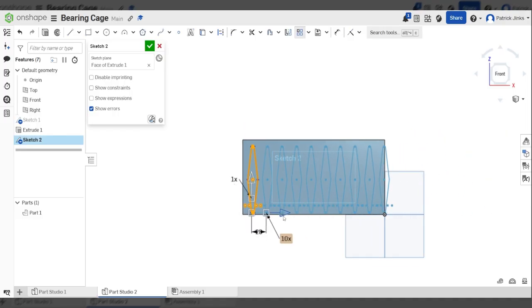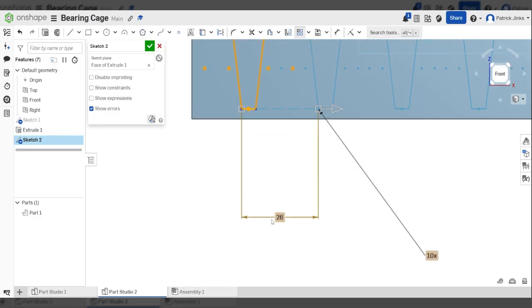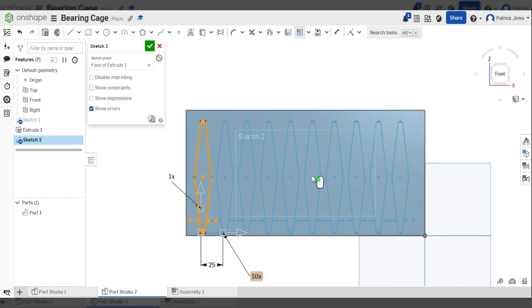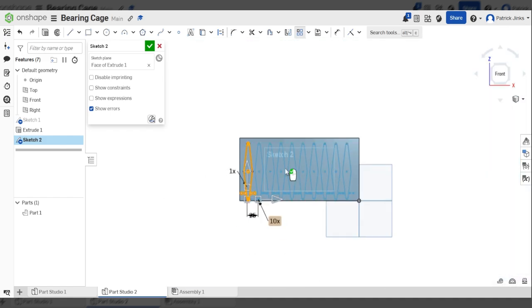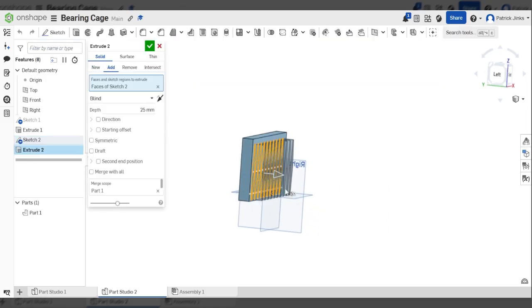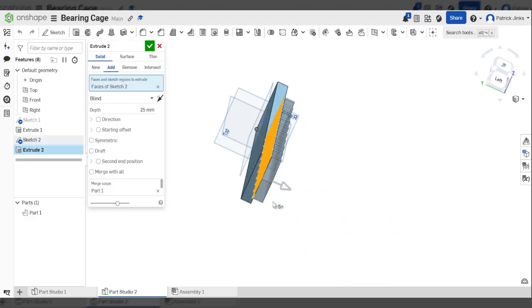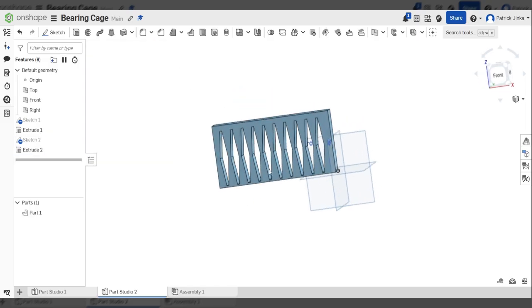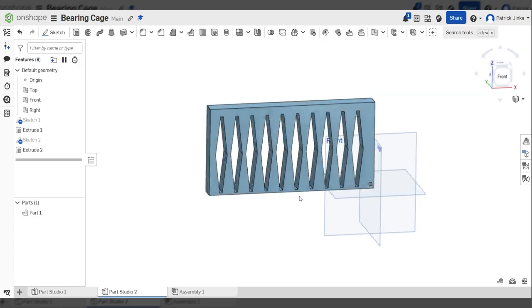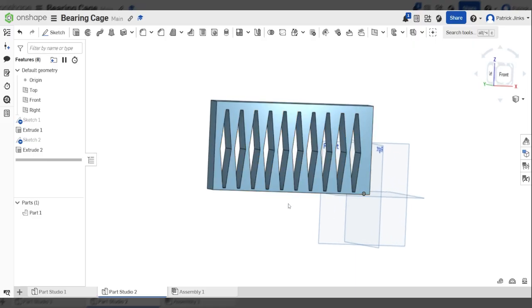And I want them all concertinaed together. I can see about how far between each one I've got. 26 looks about right. Let's make it nice around 25. It's going to put 25 mil in between each section. And when I've done with that, all I need to do is click away from my page. And then if I click extrude, for example, if I was making a grid, a grill, I can either extrude them all as one or remove them all as one. And I've used the pattern to make a sketch, a repeated sketch, to make a repeated feature in that way.